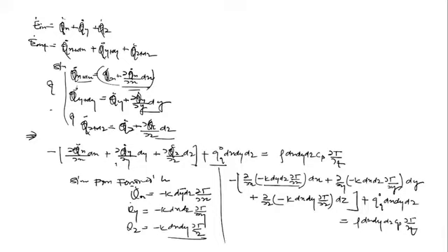Now here I am going to write a very important thing. Can you take this dy dz outside this differentiation? Tell me, can you take this dx dz outside this differentiation, because these all terms are inside the differentiation here. This dy dz is actually the area normal to the direction of heat transfer, the area normal to x, and you can take it outside only when the area is not a function of x.